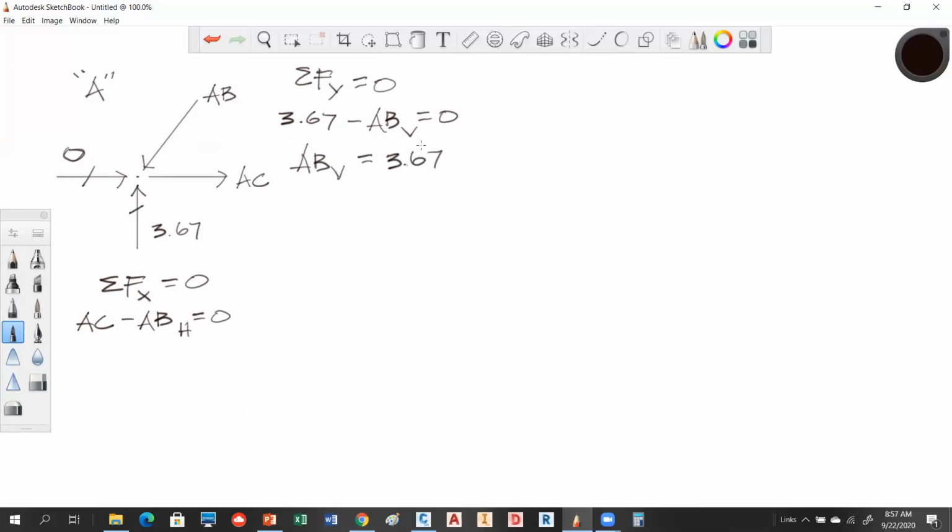See, that's not too bad. So now here's the cool thing. If you know the vert, you can solve the horizontal because this thing has a slope angle on it. It's 12 feet this way by 9 feet this way. If you go back and look at that original truss, that panel was 9 feet on 12. So you can create a real simple proportion here. Watch this.